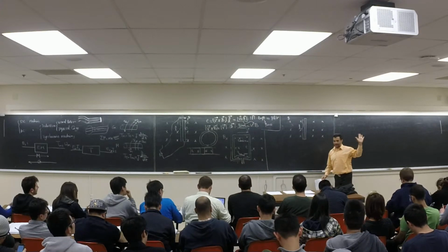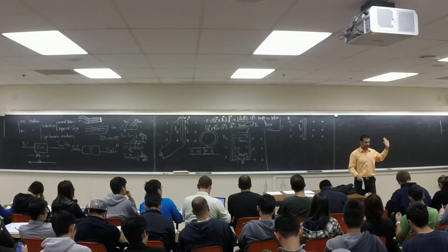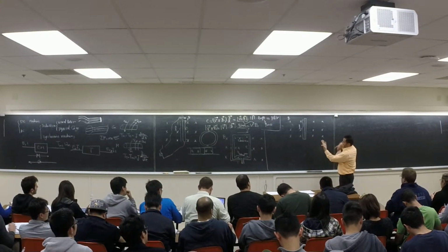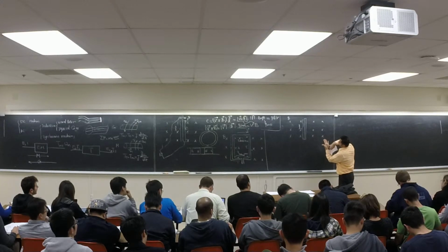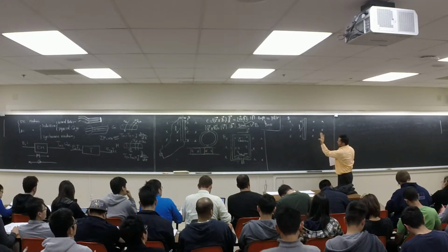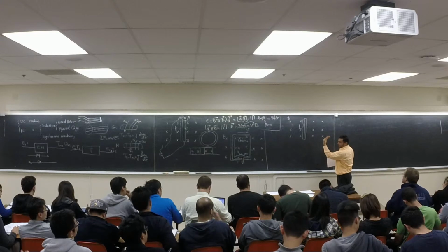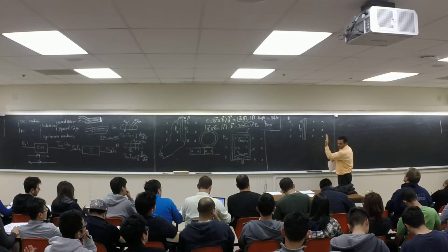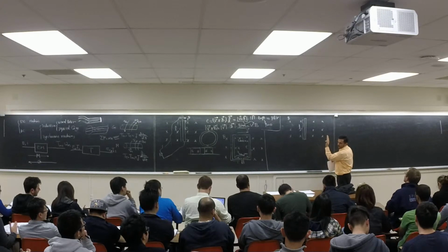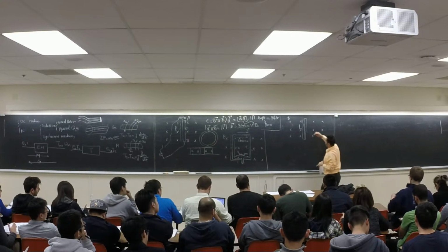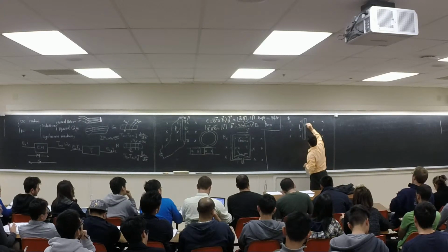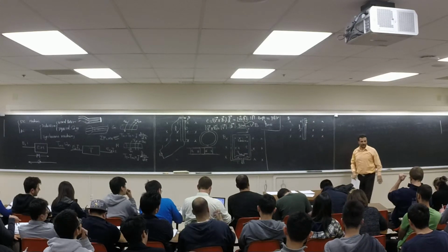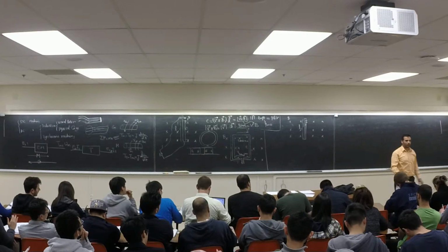For this one, we use the left-hand rule. For the generator, we use the right-hand rule. For the motor, we use the left-hand rule. So again, if the magnetic field is referring to my hand this way, and these four fingers show the direction of the current, then the thumb is going to show the direction of the force. Let's say we have a current like this in this one, right? So I want to see which way this conductor is going to move.